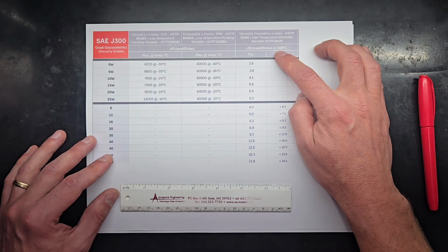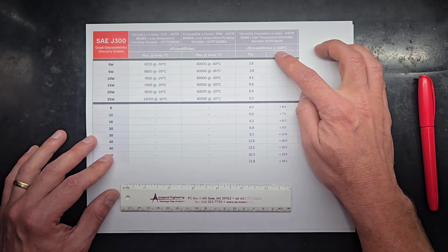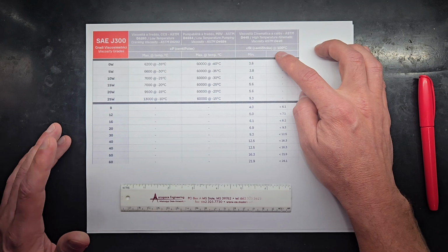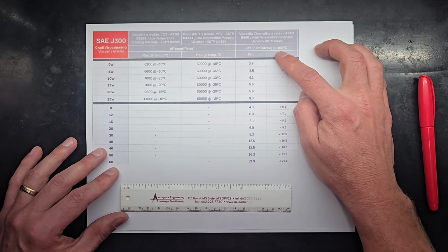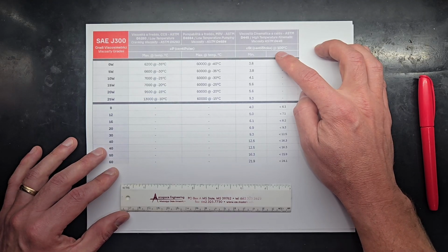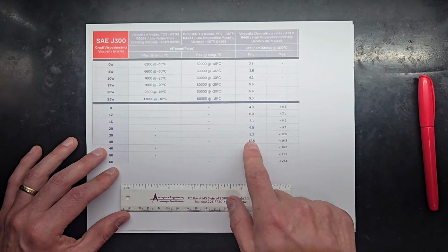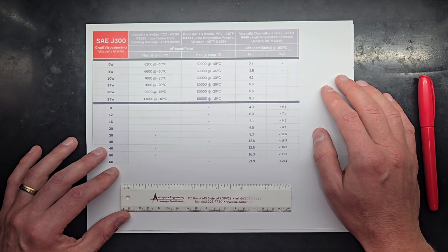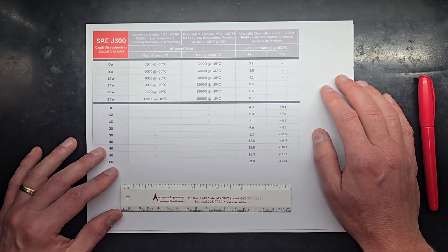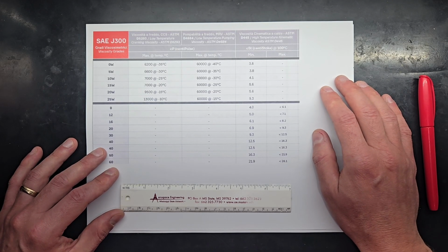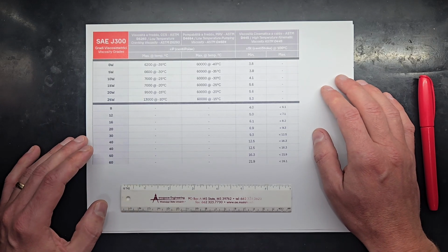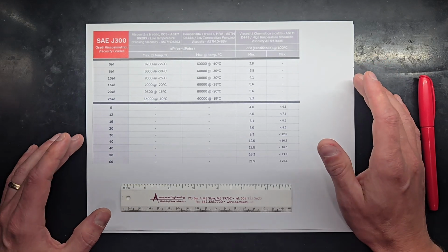The way it's done is you have a known volume of the lubricant or the liquid that you're trying to measure, and you flow it through an orifice, and you measure the amount of time that it takes for that fluid to flow through the orifice. Based on that time, that is how we establish the viscosity. The only force acting on that fluid is gravity, so its density plays a role in how it flows. That density is going to affect the force.